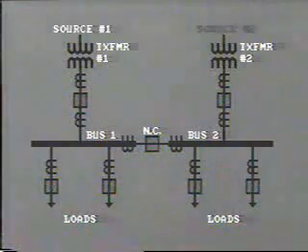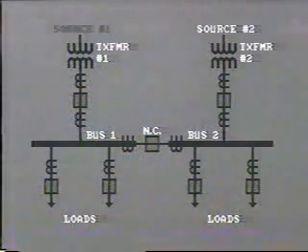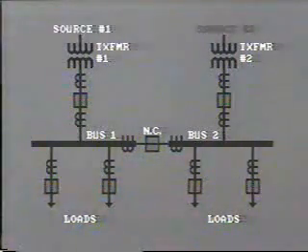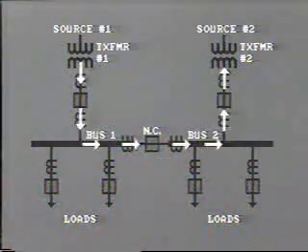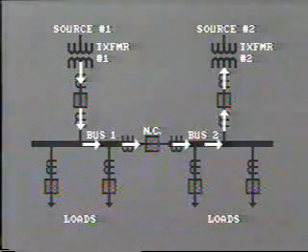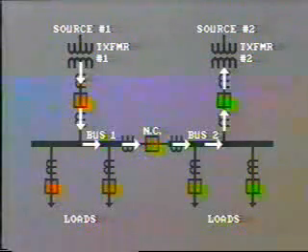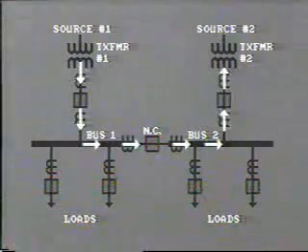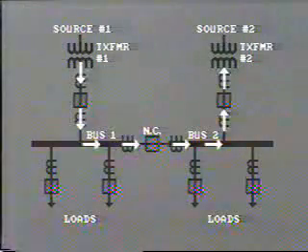For example, line 1 and line 2 may not be fed from the same bus or even the same location. Consequently, there is probably some phase difference between them. In this situation, for example, line 1 may try to transfer load to line 2 through transformer 1 along the connected bus and back through transformer 2. This is a highly undesirable situation that may allow extremely high currents to flow through the system. For this reason, you will often hear the recommendation, never connect transformers in parallel.